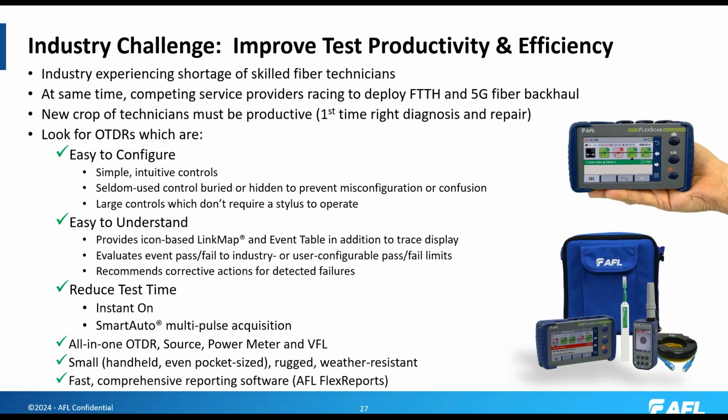An all-in-one OTDR with an optical light source, an optical power meter, and a VFL allows you to measure output power, to generate fiber identifying tones, to perform your fault locating using your OTDR, and to make your length, loss, and ORL measurements. And when you've identified macro bends, but they're not jumping out at you, you can use your red laser to try to pinpoint them.